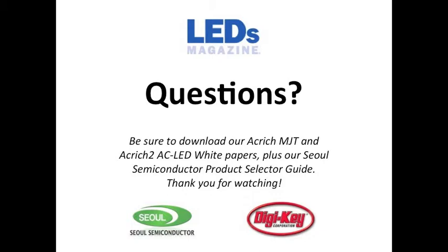You used the term MJT, which I think stands for multi-junction technology. Is that right? That's correct. That's what we're terming our high voltage family of products. We've been doing this for over 4 years now, and basically it's a monolithic array where we've grown all the die up on one substrate, and then we package it. We put those die down on a metallized sublayer to connect each of those die, so you don't have your typical wire bond between the die, which a lot of people have done in the past. So it's a more reliable system.